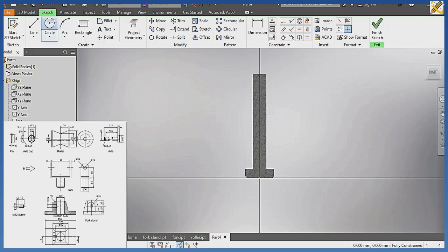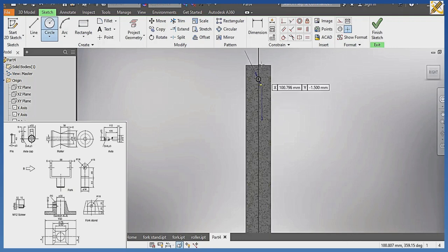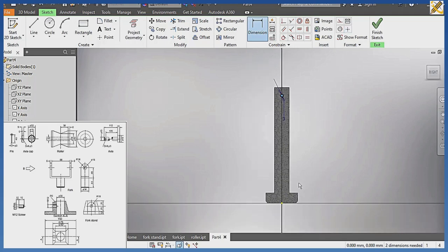Okay, I pick my circle. Picking my circle, standing at this midpoint, I draw a circle of diameter, what? Diameter 3. Then what? Enter. Then I pick my dimension. With my dimension, okay, from the center of this circle right about there to this area is what? Mark of 105. Then what? Enter, like that.